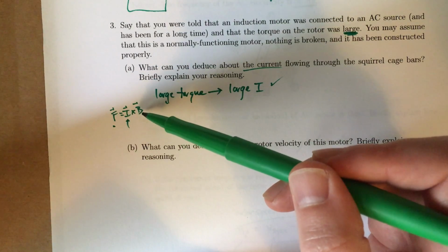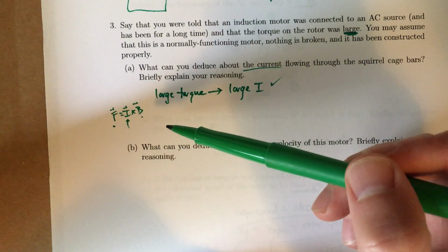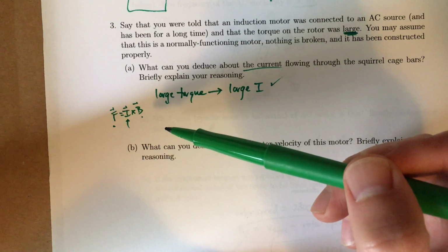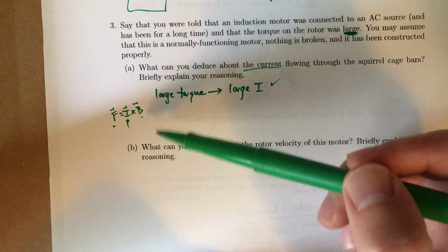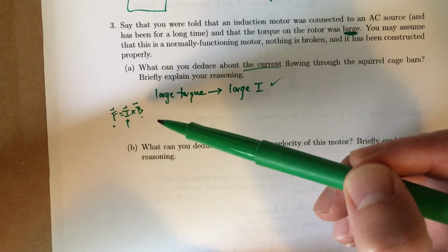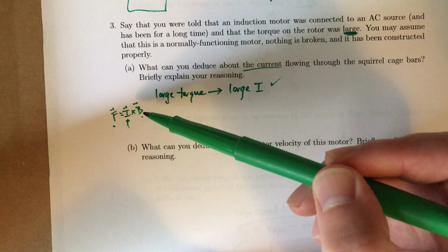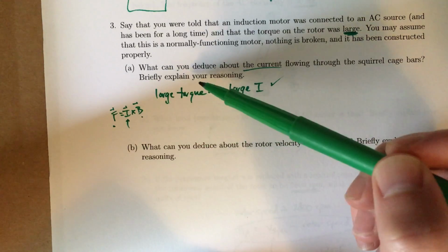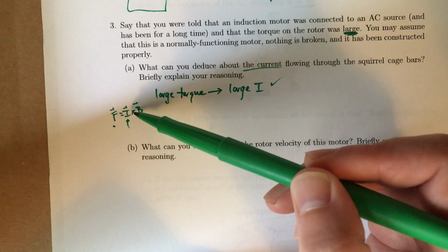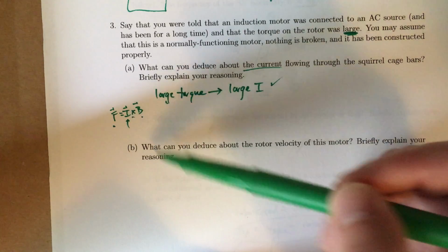It's worth saying that the magnetic field here would be changing in the case of an AC motor, right? Because the current being fed into the electromagnets is changing, and so the field is changing. But it is changing back and forth between two limits, right? You're going to go from a peak to a trough to a peak to a trough to a peak to a trough. And so, though this is a variable, if you're just told a large average torque, it's going to be the current that is most strongly affecting that. And so we can just concentrate on that.